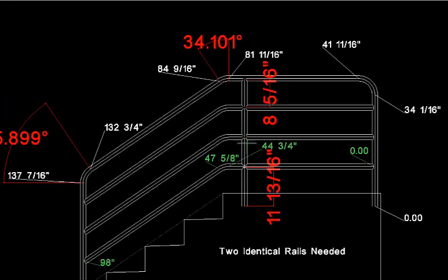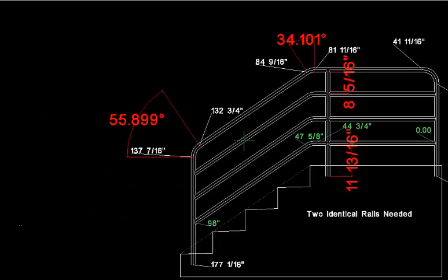I just want to show people how I build rails and dimension pipes. These are the actual start and stop of each bend that we're going to make. You can put it into the bender either way, and it comes out very accurately. It's the same thing. So it's good if you're in a tight place and you can't swing the pipe through the bender the same way without turning the bender. It's a lot of help. And that's about it.